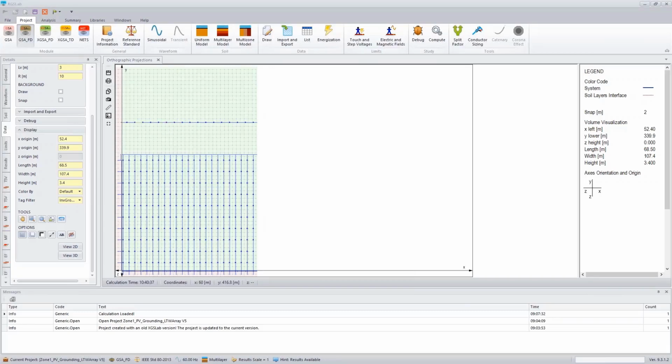So someone asked about the characteristics of concrete and how that could affect the characteristics of this post as they may be embedded in concrete. Typically, when you are installing the posts and then pouring concrete in there, the concrete takes on a lot of the soil characteristics of its surrounding soil because it matches the water content of the soil.